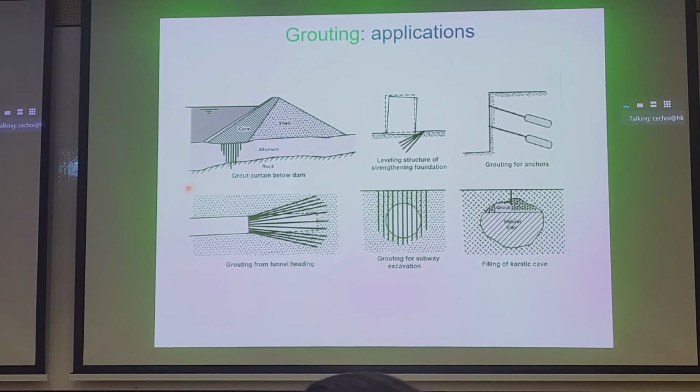The collapse of the tunneling phase can be catastrophic for your tunnel advancing machine, your boring machine. It can also affect the safety, and if you grout enough, you might be able to affect the permeability of the ground. Let's say there is an infiltration of water into the tunnel. That could be something we're afraid of during tunneling. These are all hazards that we try to mitigate.